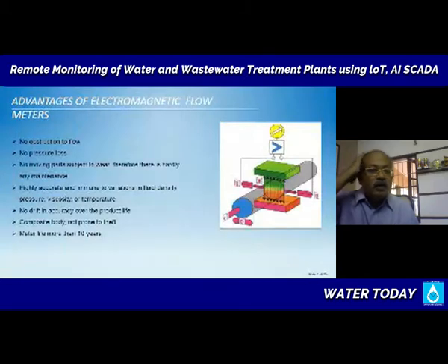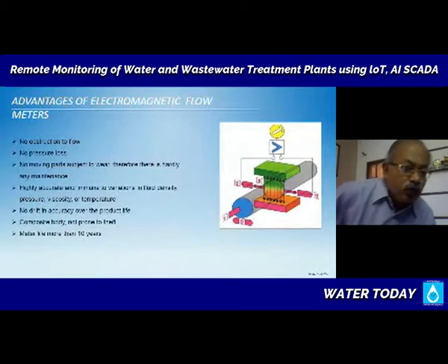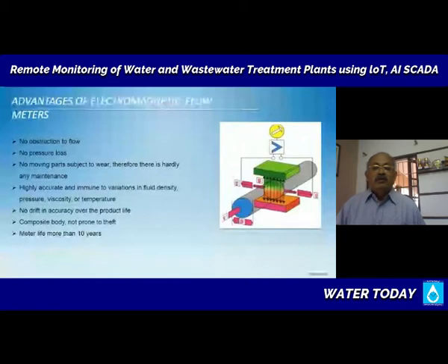Again, look at how technically it is working. There is a magnetic field and there is an EMF induced. When a conducting medium like water flows in the magnetic field, that EMF is measured and directly converted into velocity, and that velocity is converted into volume flow. So if you have good velocity, like above 1 meter per second, the magnetic flow meters give excellent accuracy and they give good 15, 20 years life performance mostly, and those are very robust solutions that you can have. But the trouble is, please watch when you are selecting your meter, make sure that you don't deploy something which is not applicable for your process condition.